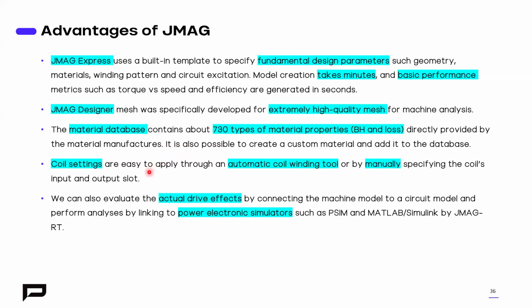And we have a very easy coil setting panel, which is easy to apply through an automatic coil winding tool, or manually we can directly import our own circuit into the circuit modeling panel. And we can also evaluate the actual drive effects by connecting the machine model to a circuit model, and perform analysis by linking power electronic simulators like PSIM, MATLAB, Simba, and other third-party software.